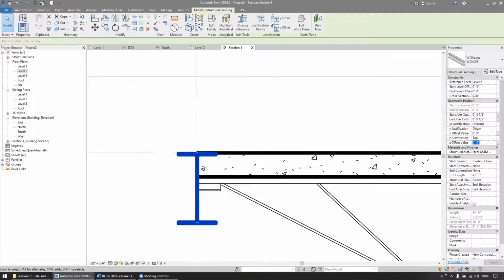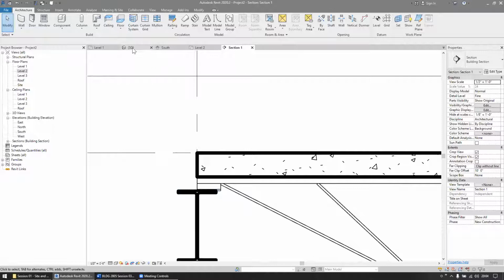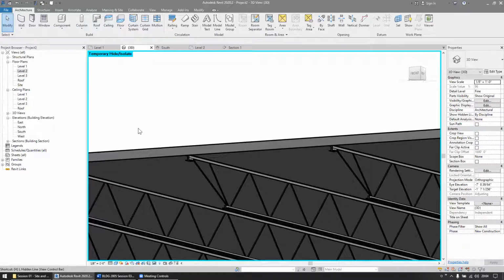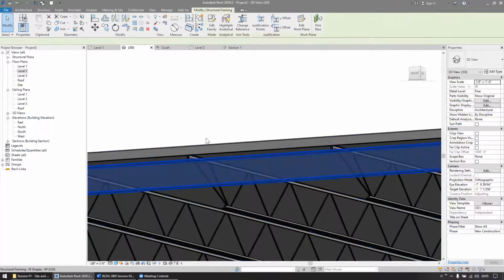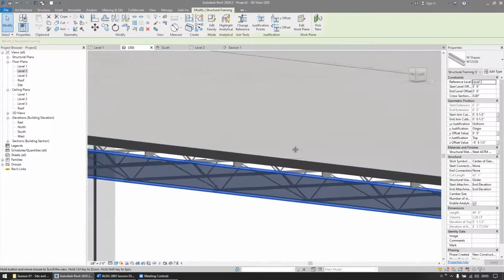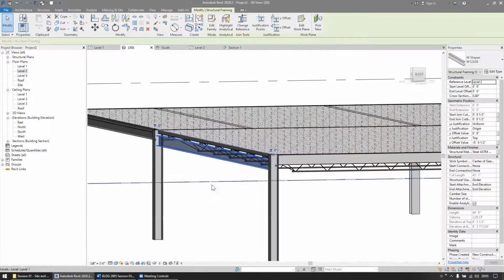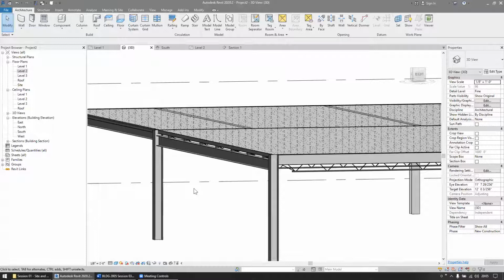So in here, we can specify a negative 6.5 inch Z offset for that beam, and now it's sitting at the proper elevation. So I just did a reset there, and you folks can see that indeed our steel beam is sitting at the right height. So when you folks are putting the steel structure into a building, if you're going to model that, then just keep in mind where all of these different bits and pieces sit.